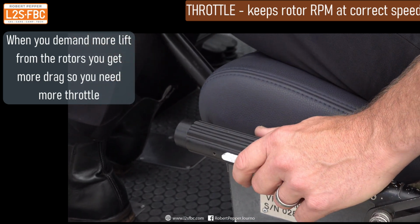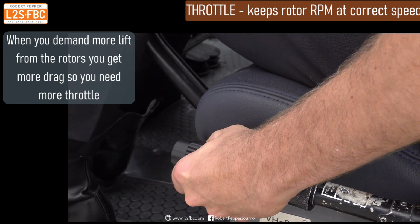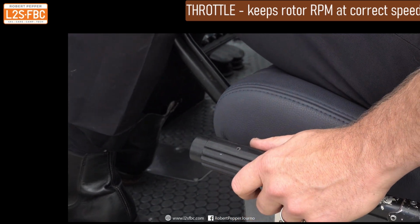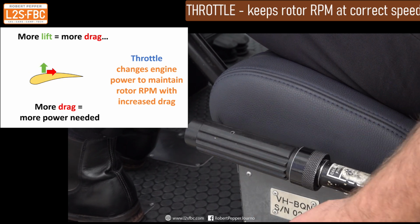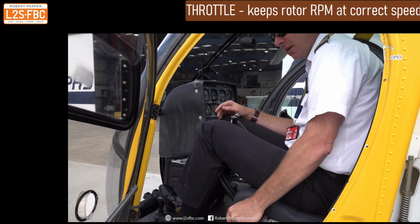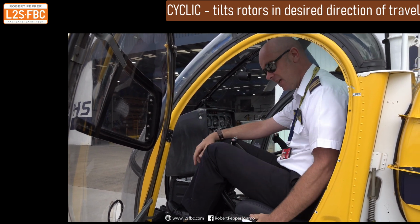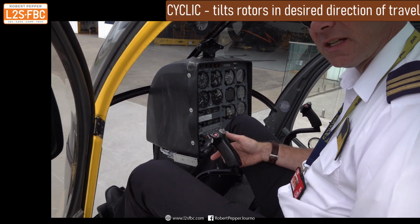At the end of the collective that we just discussed, we got this little bit here, which is called the throttle. It's very similar to an accelerator. You open the throttle, in this case away from you. It allows more fuel and air into the engine, and you increase the power, and as a result you increase the rotor RPM, and the machine will either go faster or will go up and climb. As such, you close the throttle by merely winding it back towards you. You reduce the amount of fuel and air into the engine, reducing the power, and your rotor RPM will start to decay.